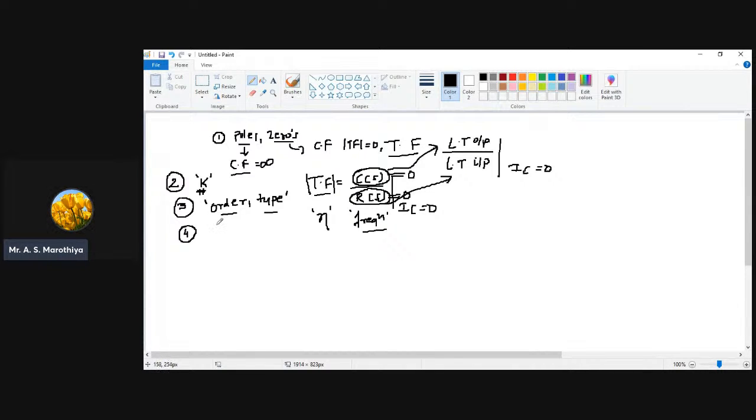That means in order to find the stability of a system, first and most important, we must know its transfer function. It may be an open loop transfer function, it may be a closed loop transfer function. But in order to find the stability of a system, by applying any technique, it may be Routh-Hurwitz criteria, or root-locus technique, or Bode plot technique, or Nyquist plot or polar plot, while applying these techniques we must know the transfer function of the system. Hence, transfer function plays an important role in identifying the stability of the system.